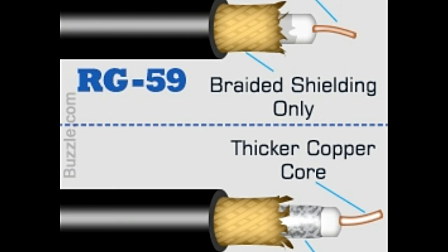Selection of coaxial cables. RG59 cables are best used where transmission distances are short, and the frequencies used are lesser than 50 MHz. Therefore, they are ideal for CCTV security camera networks. Using frequencies larger than 50 MHz will cause electromagnetic interference and degradation of the signal.